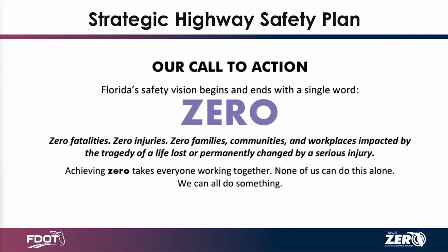Once they leave the roadway, we're making sure they can get back. So whether that's a shoulder, good cross slopes, or not putting obstructions in the way, they have time to get back on the roadway. Safety Edge: if there is a maintenance issue or washout on the edge of pavement, they can still get back on without having to really fight the car. And then reducing consequences. So that's the frangibility of what we put out there, making sure breakaway features are done properly, and that we're protecting the features adjacent to the roadway that we can't move out, right?